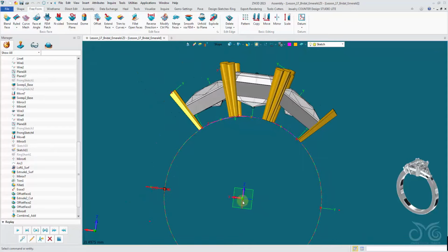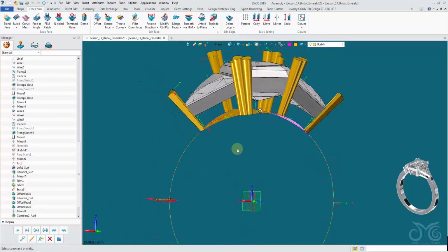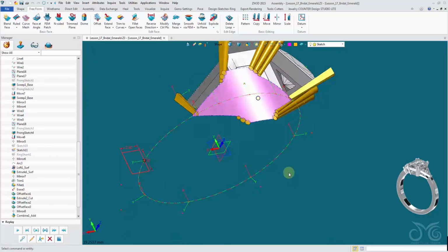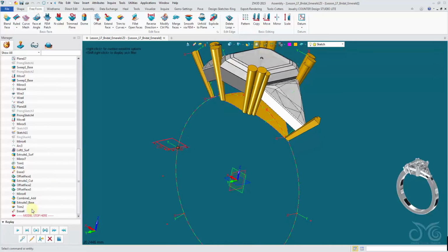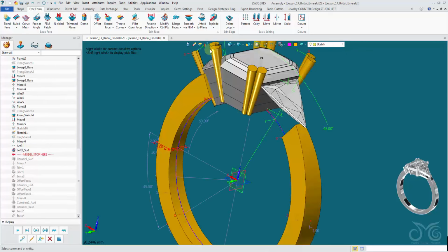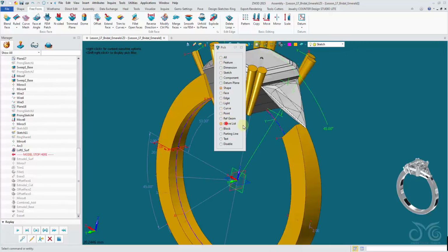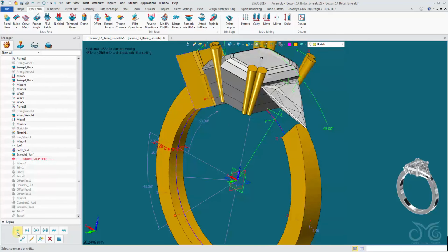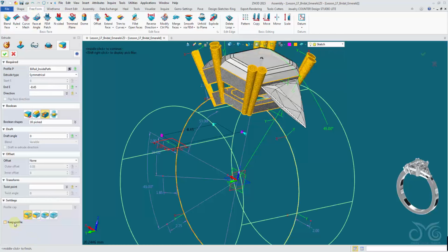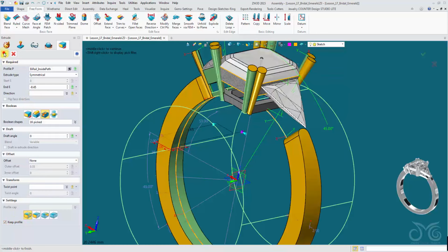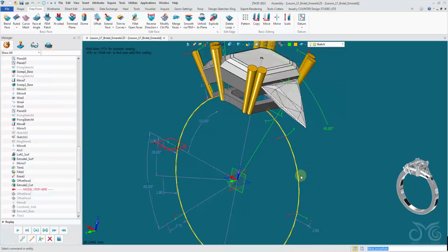Okay, now what I probably should point out actually is if we were to have extruded with that curve list, we may have got a seam line. So let's see if I can recreate that. Okay, so we have our curve list here. I'm just tracking down where it disappears. Okay, it was that extrude. I must not have kept the curves. I want to keep profile to keep that curve list.